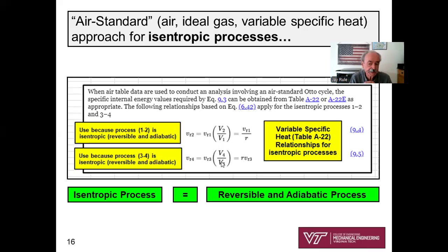Go back to our sketch. Well, how am I going to get v4 and v3? That wasn't given. You look at the power of the sketch, you're going to see that v4 over v3 exactly equals v1 over v2. So I hope that planning helps. We're going to use these vR lookup values. These are properties. vR is a property. We're going to look that up in table A22.